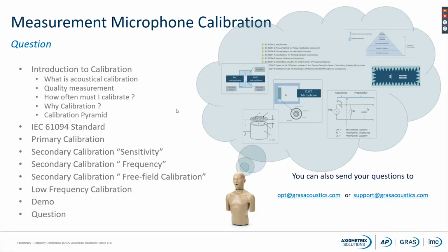The open circuit sensitivity, as you saw in the demo system, has a time constant from when you apply the polarization voltage until the microphone is 100% stable. It's about 30 seconds.